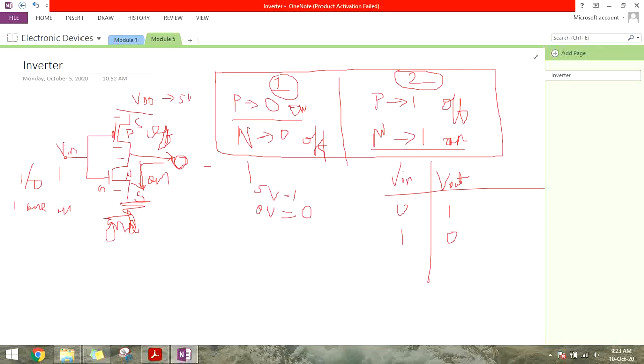One of the important applications of this CMOS inverter is ultra low power consumption. Since it uses very little power, it is used in digital applications such as electronic watches, where you need very little power consumption, or else the battery life will not be good. It is also used in ultra large scale integration, since millions of transistors are integrated on a single IC. The power consumption of each transistor matters a lot. If millions of transistors consume more power, then the power dissipation will increase. Since the CMOS inverter consumes very little power, it is very useful in ultra low power applications.